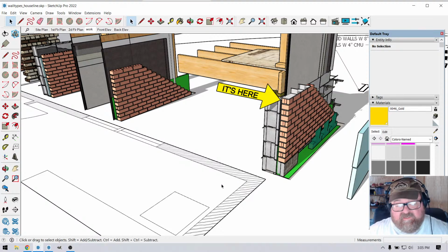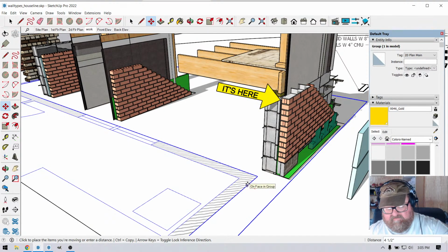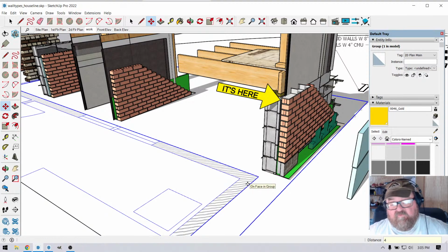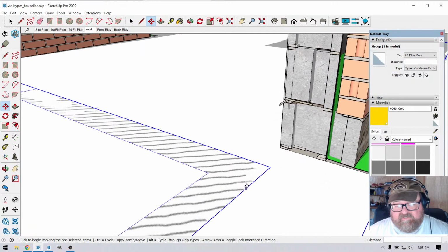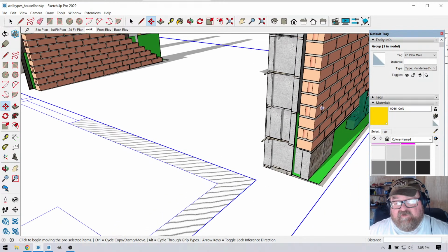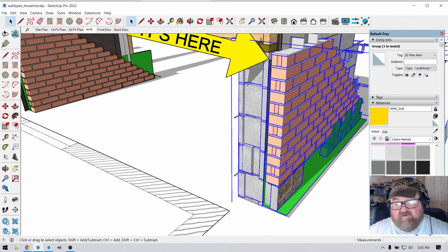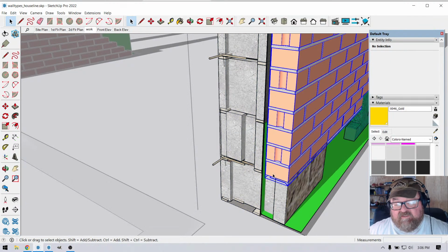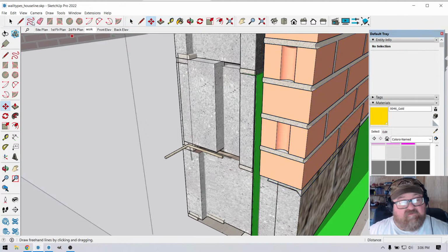So if I'm going to have brick, I'm going to set this back. I might even set it back 6 inches if I've got room, but I'm going to do a minimum of 4. Okay, but I'm still going to dimension, and we'll get into that in a second, I'm still going to dimension from the house line, not the face of the brick. Because honestly, when the brick mason starts laying brick, sometimes they actually do leave a little more. Sometimes it actually hangs over.